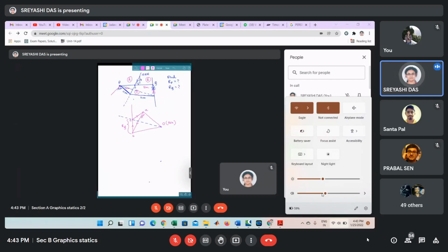And from this force diagram, you can find the horizontal and vertical component also. So this thing will denote RP. And if you want to find out the horizontal and vertical component, then you have already drawn the vertical line BC extended. Now draw a horizontal line from A. So if you name this as E, for example, this will give the vertical component of RP, and this will give the horizontal component of RP.